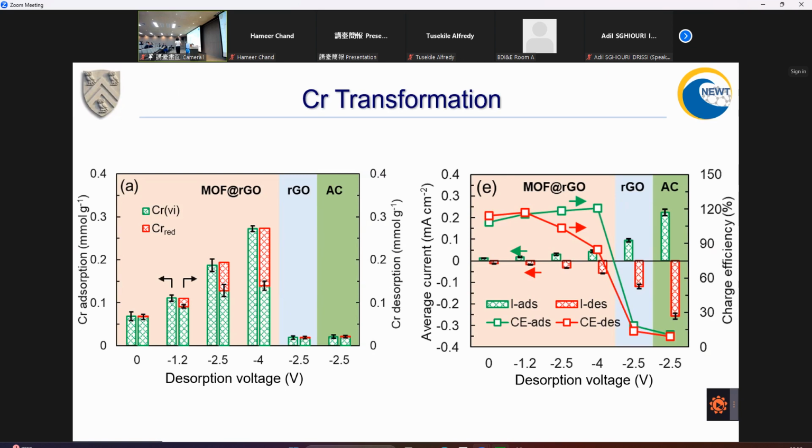And the impact of desorption voltage is also showing here with increasing charge efficiency when you go to higher desorption voltage. So we are actually exceeding 100% charge efficiency. Okay, so this is a weird way to show that you have more than 100% charge efficiency. And again, this is because you have physisorption that's not caused by the electrical charge on the electrode. And when you use a high desorption voltage, you regenerate this absorption site, so you end up with higher than 100% charge efficiency.